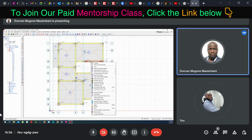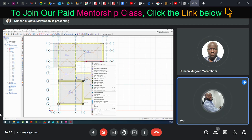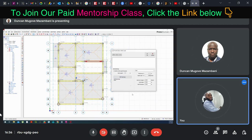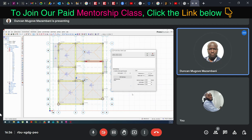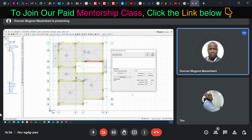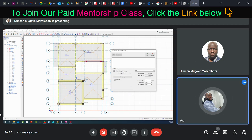Okay, now click on Define. Now click on edit beam wall load. Edit beam wall load. Okay. Are you there? Yes, yes. Okay, now on this place called unit weight, what unit weight?